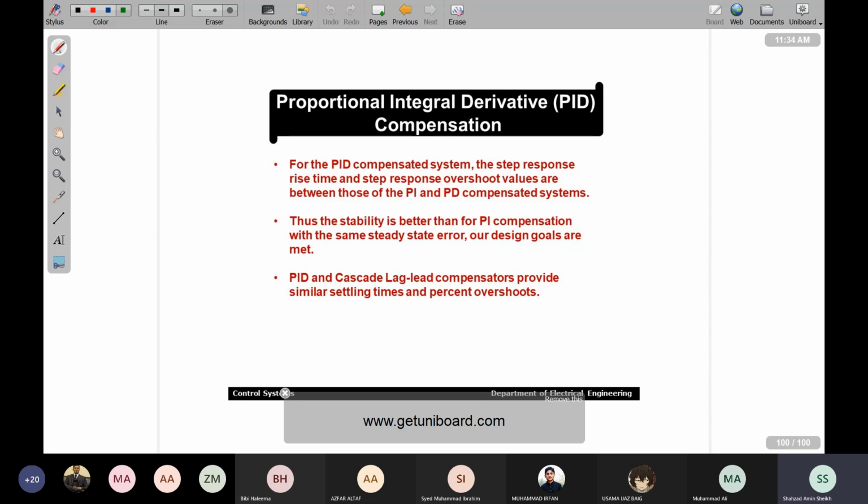And in this case, of course, the design parameters are k and a. You start your design as we have been discussing it again and again कि आप अपना k जो है आप रखते हैं जो आपके पास अनकॉम्पनसेटेड सिस्टम का होता है, आप वहाँ से इनिशियलाइज करते हैं अपने k को, और उसके बाद you are looking for your a. So you make your transfer function and root locus which is dependent on a. So आप वहाँ a की वैल्यू को चेंज करते हैं and you go for the maximum relative stability. Once you find that a, तो आप वापस आते हैं अपने ट्रांसफर फंक्शन पे, वहाँ पे अब आपके पास a की वैल्यू मौजूद है.